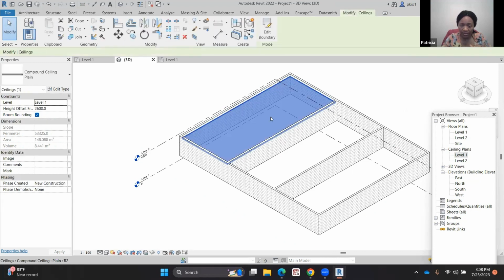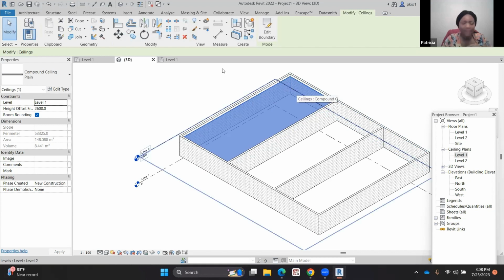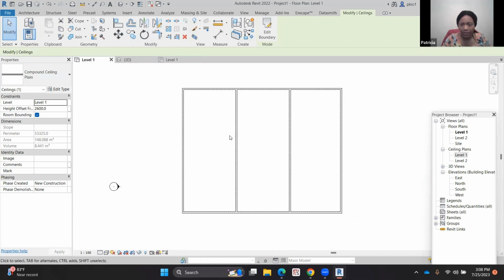And then if you want to select it, you select the ceiling in that space. So the next one we want to do is the sloped ceiling. So for that, I'll put a roof and then I'll make it slope to that roof slant. So I'll go back to level 1 here, and then we want to look at the heights we have in the drawing. So we can do that by section or by elevations. We've shown the elevations, you can click any of these.